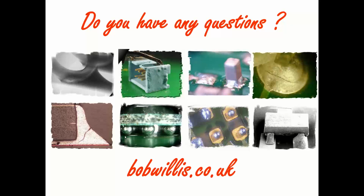Okay, that's another good, interesting question. Are there any compelling reasons to coat plastics and other non-metals? Or the bottom line is you've got to think about what impact not coating is going to have on the environment you're going to use it in. So if we step back for a second, the most common reason we get failures is dendrites and corrosion.